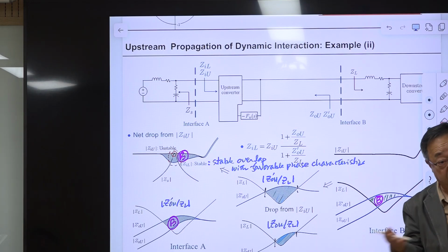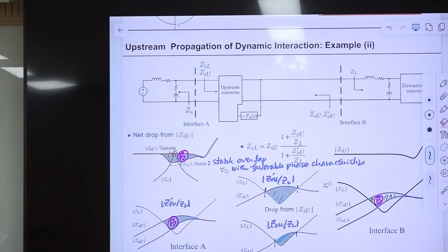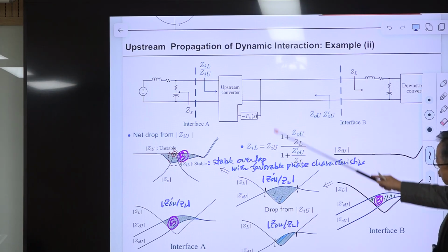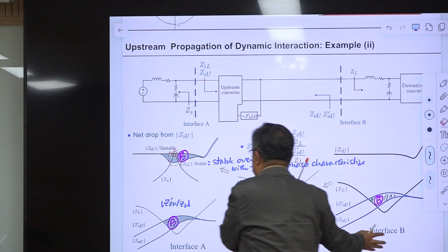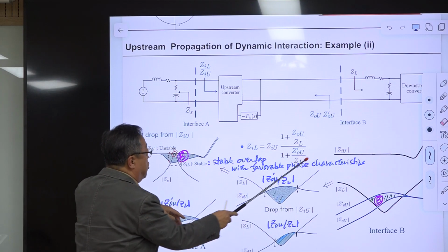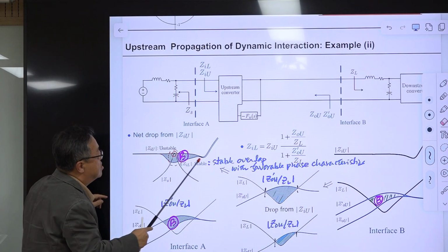That was very tedious, very painful and very difficult. I had a long derivation. With some approximation, I found this. In the voltage mode control, the magnitude positions of these have been swapped. Previously, this one was up and this one was down. For this case, this is the drop, because this large overlap comes in the denominator, so the drop is bigger. This is the peak. The peak is smaller than the drop, so it will propagate to this through this equation. Then there is just this dip.